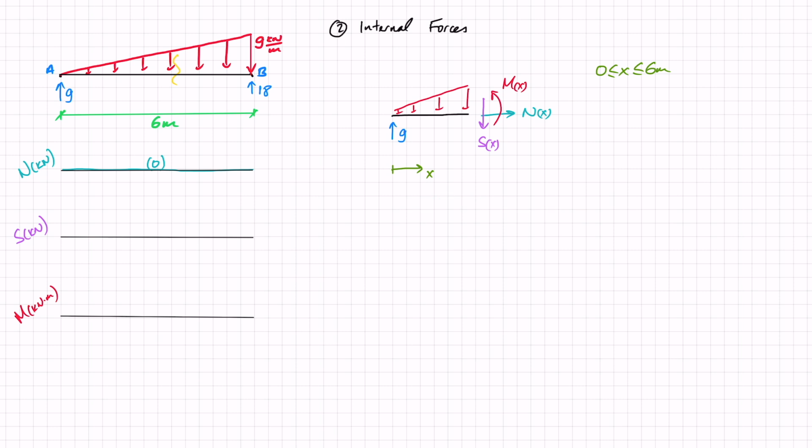The next thing that I want to find is my shear force. Now, this is something that is quite important to understand. As we mentioned before, the force at any given point is that area, the triangle. So if I'm at 1 meter, it's going to be a triangle of 1 meter. If I'm at 2 meters, it's going to be the area of the triangle for 2 meters, and so forth. But at each of these distances, I will have a different height.